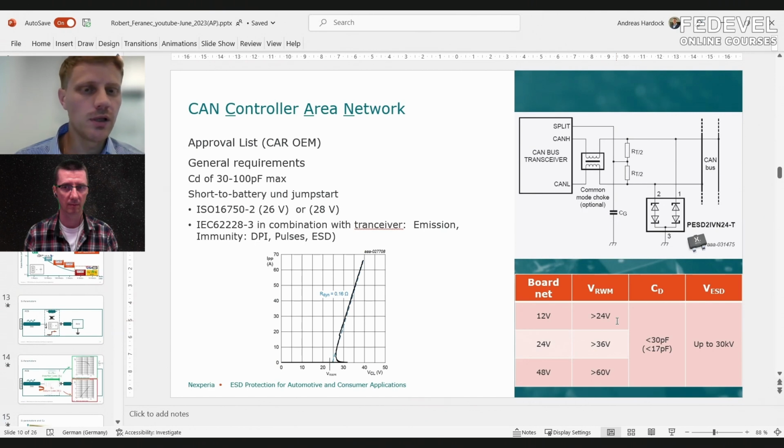So it's not critical, but then you might have some other modes which allow going up to 3.3 volts on your lines, and you need to be prepared for this. It would not be good to turn on the ESD protection devices during this.